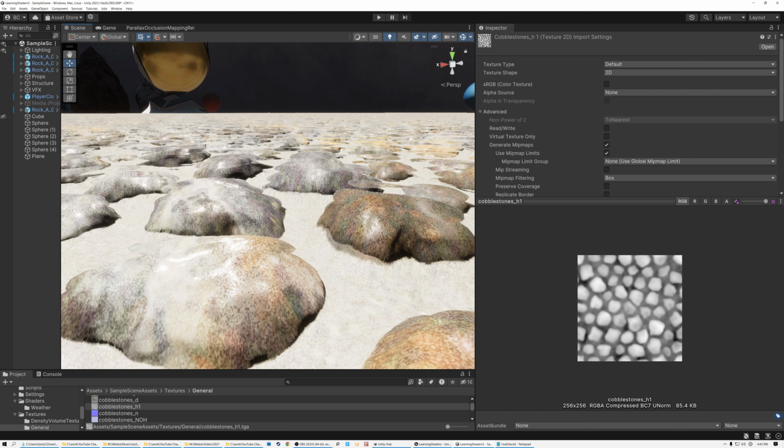You can see if I come down here, zoom in really close and get a nice steep angle, these sides of my cobblestones are really nice and smooth, and that's because I'm using 128 steps to create this effect. Now, if I reduce that number, let's just set this to something like 5, for example. And now you can see that the quality has been reduced significantly. It starts to look like my cobblestones are made out of a stack of pancakes.